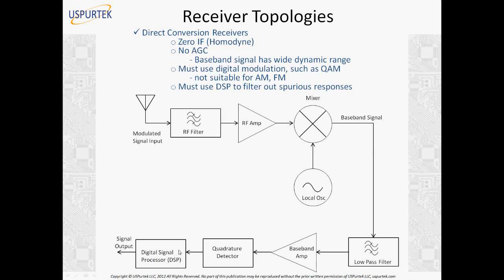By modern, I mean the cellular communication receivers, the LTE receivers, the wireless LAN receivers, all of them have direct conversion receivers. Because it's more cost effective and because the processor is readily available in these devices, in the handsets. The older radios didn't have a processor. Your car radio may not have a processor. It is just an analog AM or FM receiver, that's it. But in the case of a handset, you already have a processor inside and you can implement DSP techniques to compensate for gain, selectivity and other benefits that we earlier had with superheterodyne receivers. But the benefit is we make it more affordable, more cost effective and more applicable to digital communications. Okay.